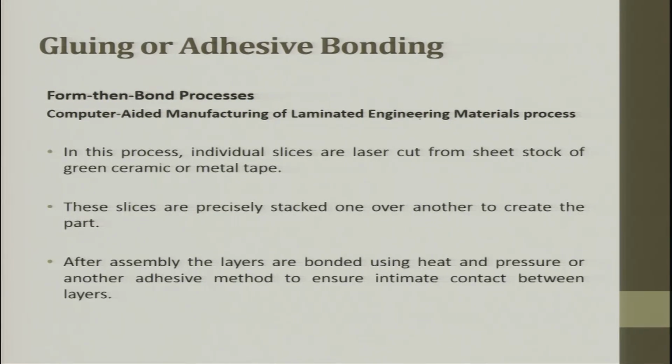Computer-aided manufacturing of laminated engineering material process. In this process, individual slices are laser cut from sheet stock of green ceramic or metal tape. These slices are precisely stacked one over each other. This is what I said is a limitation. Placing it is a challenge.